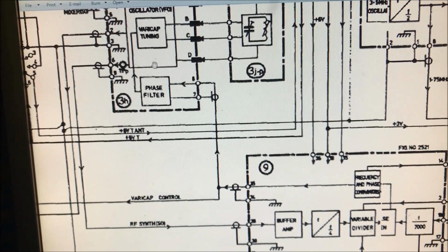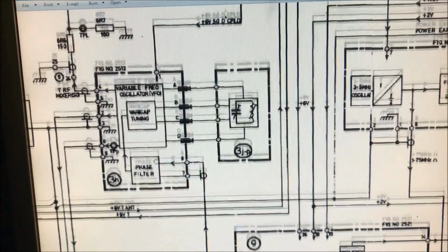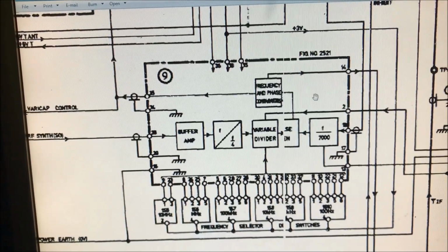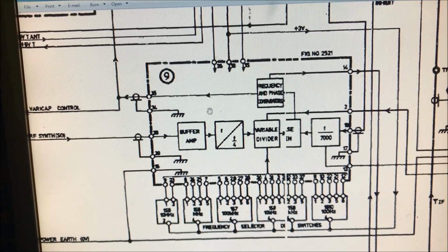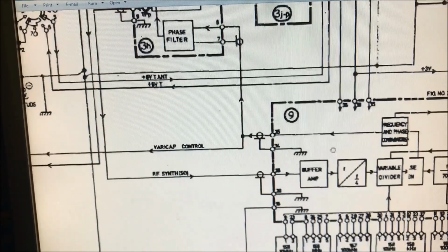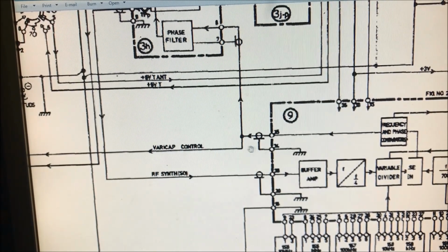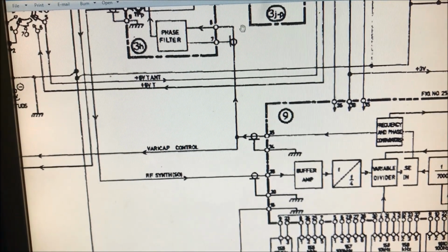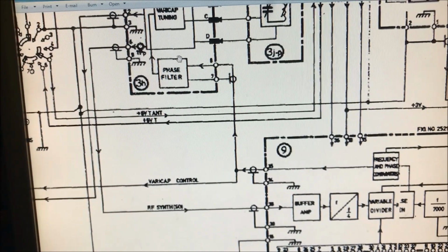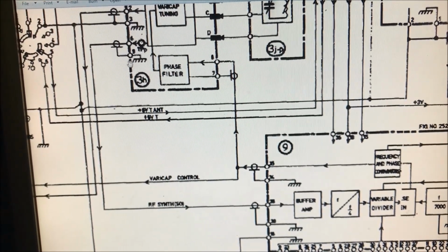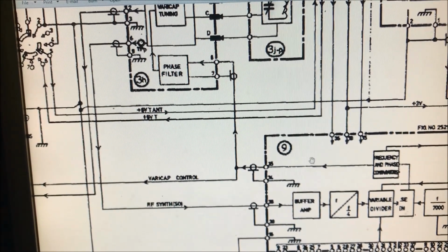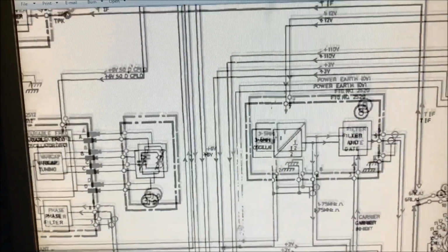Yeah, so who's at fault? Is the fault up here with the 3H board, or is the fault down here with the synthesizer? What comes first, the chicken or the egg? Who knows? So constantly the DC voltage here, the control voltage, if that's wobbling, then the whole system's going to be a wobbling system.